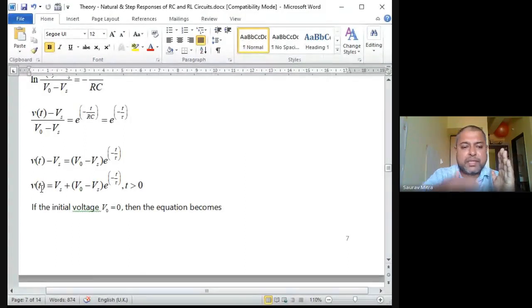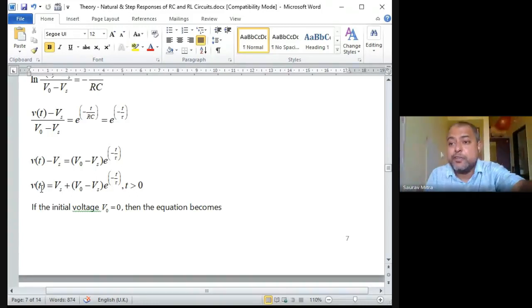Here there is 5 volt, the resistance value is 0, and here there is a capacitance. As soon as you connect the 5 volt to the capacitance without any resistance, instantly the capacitance will get charged to 5 volt. Because RC is equal to 0, there is a very big chance that as soon as you connect a very high voltage to the capacitor, the capacitor might blast as well. That is why we control how we want to charge the capacitor. How the capacitor will get charged is given by this graph, and we have to actually plot this graph.